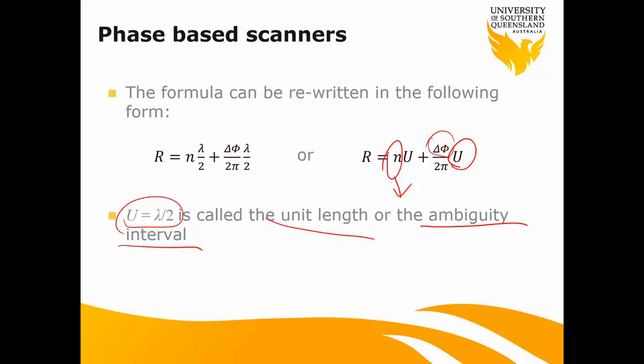This one is the phase shift we can measure. So the only thing we can measure is here, the difference of phase. And this one we know, once you determine it from the laser beam frequency used in the laser scanner, that's the modulation wave frequency, not the carrier wave. So the only thing we can measure is this one.